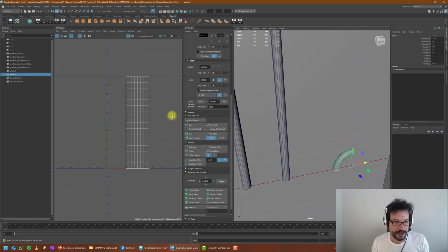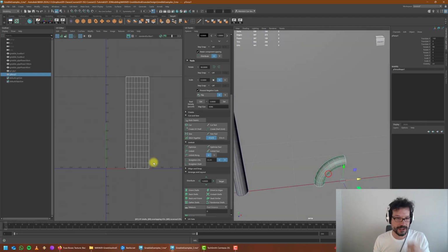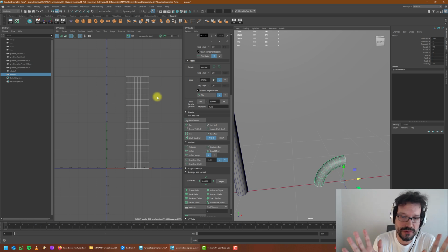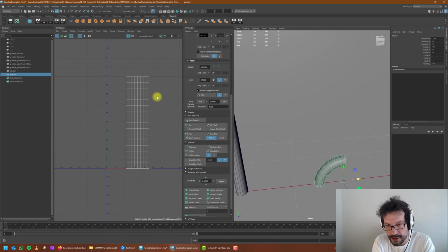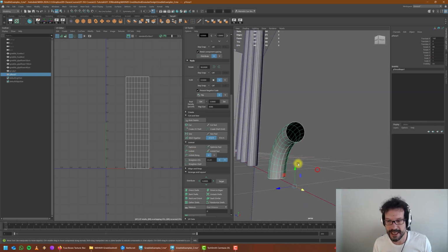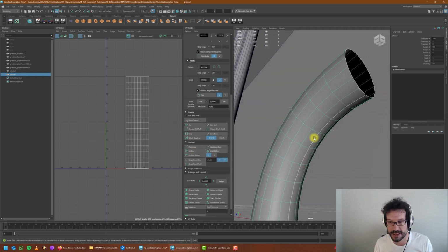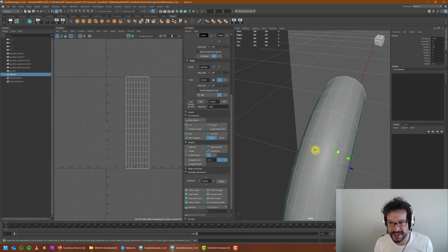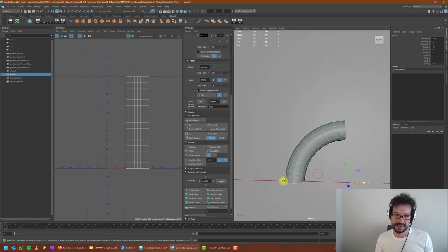When you are creating a torus like this, the UV map at first is going to appear really nice. In this case, it's going to look very straight. But keep in mind, unfolding this will bend it in and misshape it in unexpected ways. Why? Because the area of these faces right here is smaller than the area of these faces on the other side of it, because the distance is greater here than it is here.